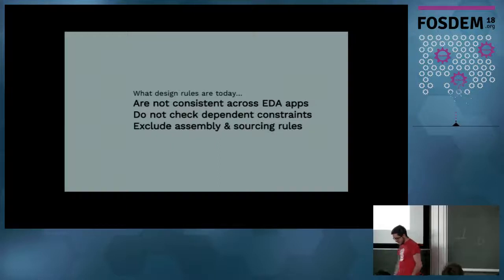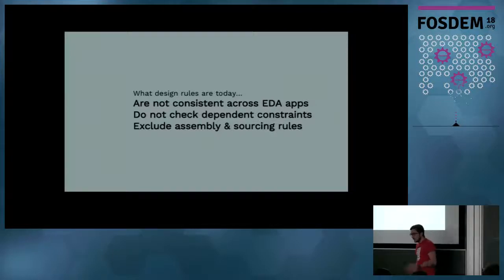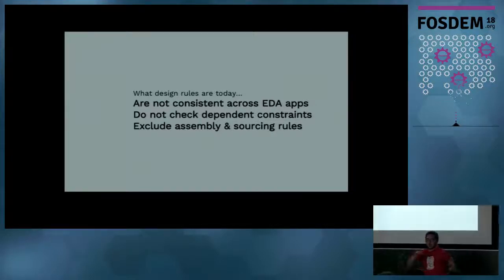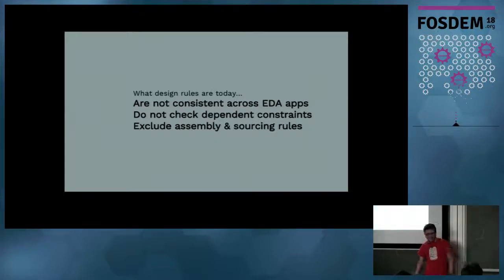Some things which bother me: for some EDA applications, there is not even a file format. So talking to the KiCad guys around here, if you do design rules in KiCad, you have to type them in by yourself. So you get some kind of PDF from your PCB manufacturer, which tells you about the limits, and then you type them into KiCad. And this is something I really like about Eagle, that you can just download the file and insert it into your drawing, and then it's done. So I have no clue, maybe I can ask later, why KiCad does not have anything like this. Maybe this is a chance to change that.